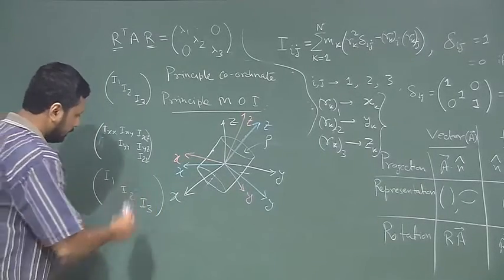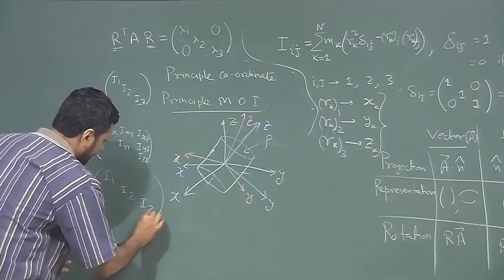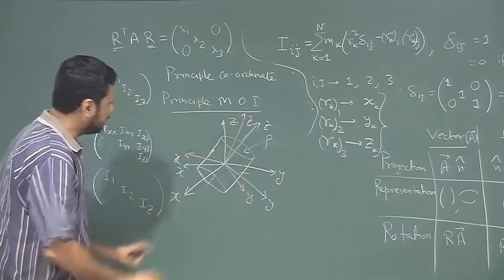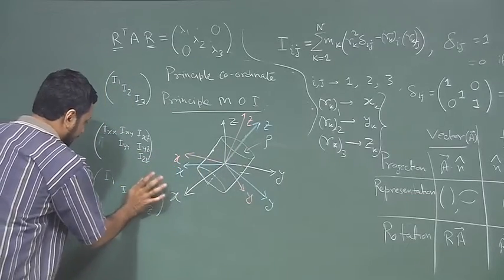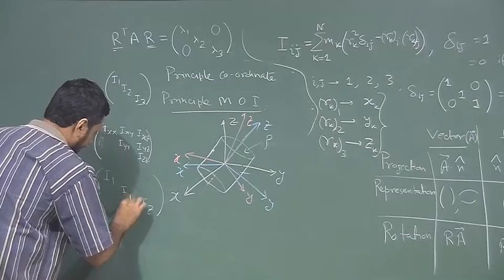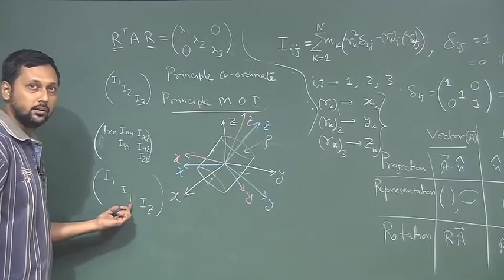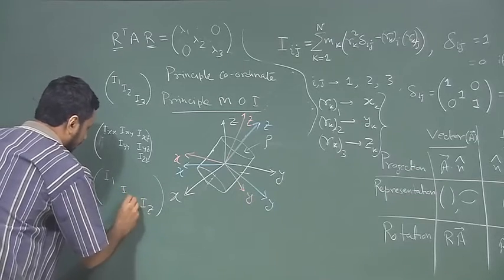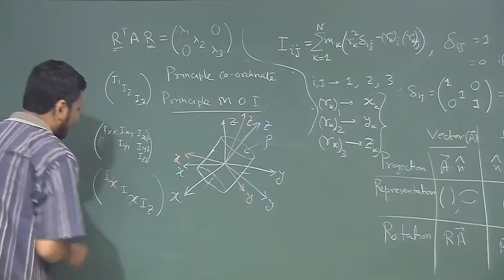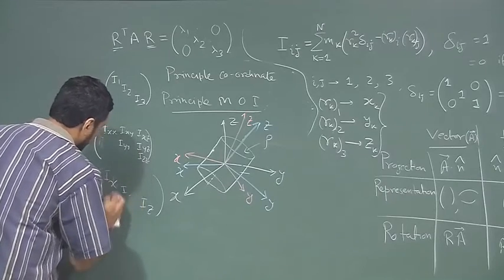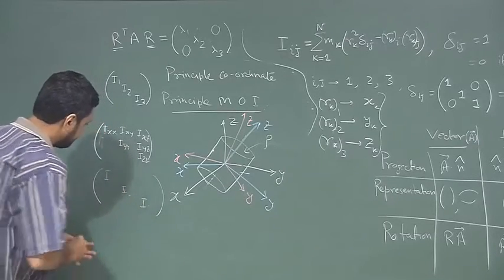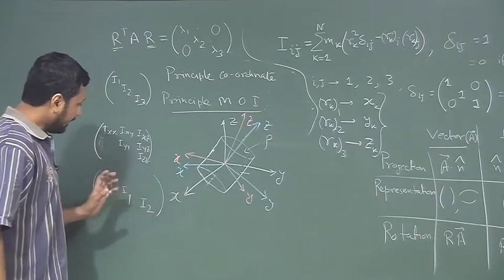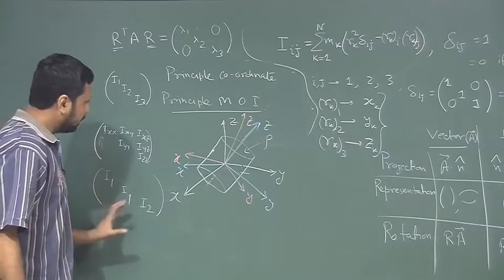So, I3 will be Iz in this case, and also I can tell you something, because the density is uniform and it is a proper cylinder, I1 and I2 will be equal. So, I am not writing I2 here, because I1 and I2 will be equal, we can just call it Ix and Ix, or what is more convenient is we just call it I1 and I2.